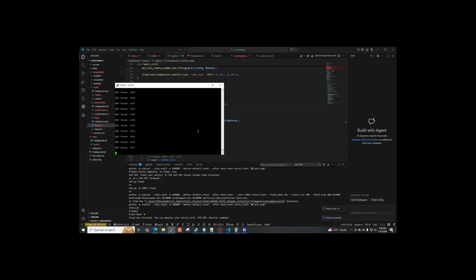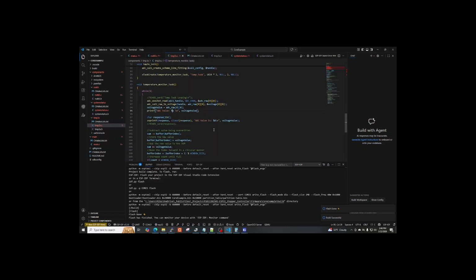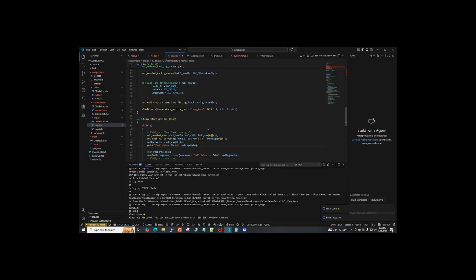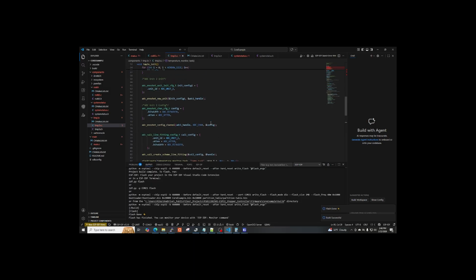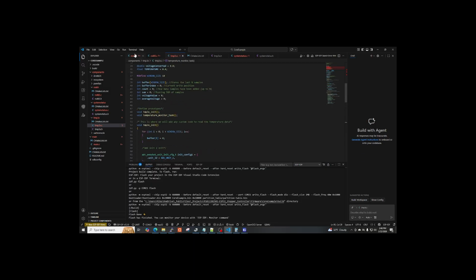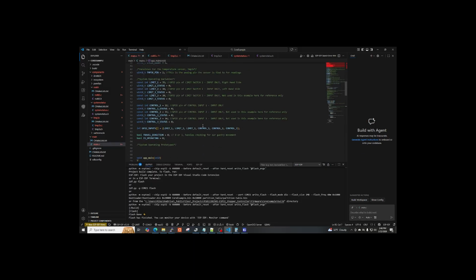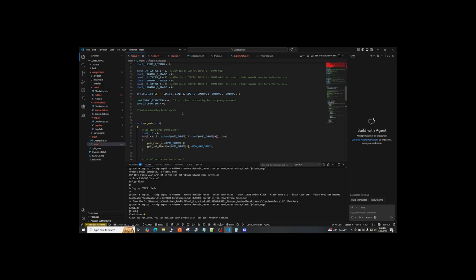Heating it up is increasing the voltage value. Okay, all right. So it is one of the subsystems interfering with this ADC. All right. So that's a positive. So let's figure out which of these subsystems that we're bringing up could be interfering with it.